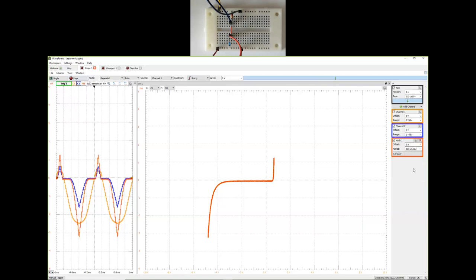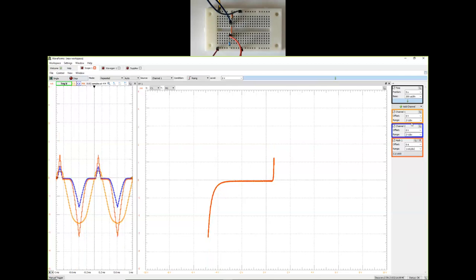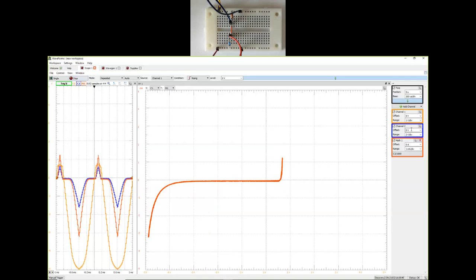Let's see if that becomes too much. Maybe I can do this with the voltage. Channel 1 voltage, I hope if I can go to 1 volt per division, I'll still be inside. Okay, I'm still inside. So that's the IV characteristic of a Zener. And when we started this, we expected that to be doing that. On the positive side, similar to small signal. On the reverse side, breaks down at a relatively smaller voltage, close to -5 in this case.